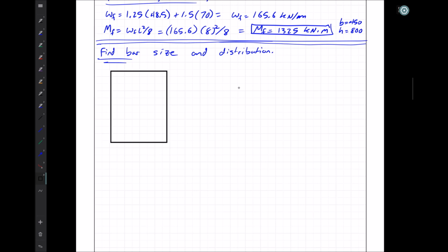If we've got our beam, and this beam has inside of it stirrups. These are our transverse reinforcement, and these are specified at 10 M bars, so these are 10 M stirrups, which would have a bar diameter of 11.3 millimeters that we can look up in the table in the concrete handbook. On top of those stirrups, we're going to place longitudinal reinforcement, and there's a possibility that they could be in 1 or 2 rows.